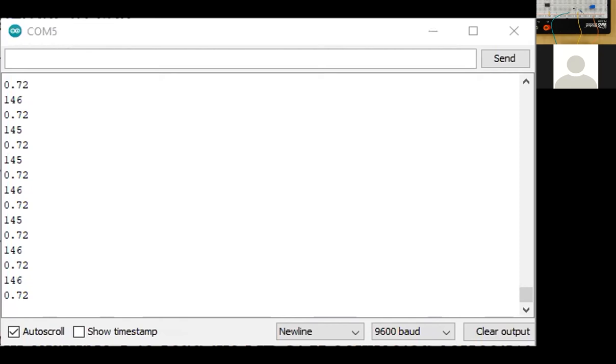Now, the reason we're looking at this is we're going to use this as a temperature sensor later on. If I squeeze onto this diode and hold it, I'm just heating it up with my hand. You can see that voltage changing a little bit. Not much, obviously, because I can't heat it up a bunch, but I got it to change from like 0.72 to 0.7. And if I let go of it, I should be able to make it change back. Later on, we're going to build the amplifying circuit to make that a full temperature sensor.